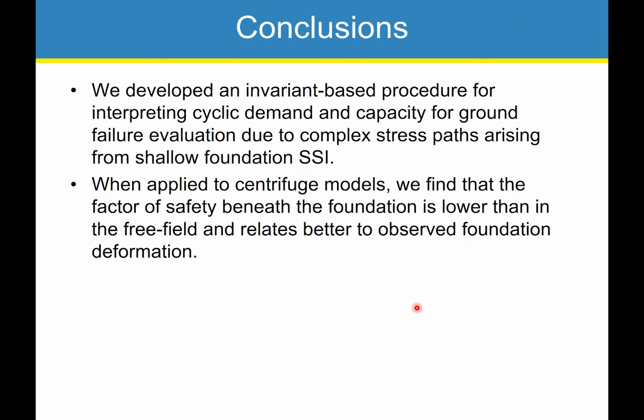So our conclusions, we developed an invariant-based procedure. We took complicated stress fields beneath footings, computed the mean stress and the deviatoric stress invariant, so 2 invariants, and we reframed the cyclic stress ratio in terms of those invariants instead, to allow us to use those invariants to compute an equivalent CSR quantity that can be used for ground failure analysis. So it accounts for the complex stress paths arising from shallow foundation SSI.